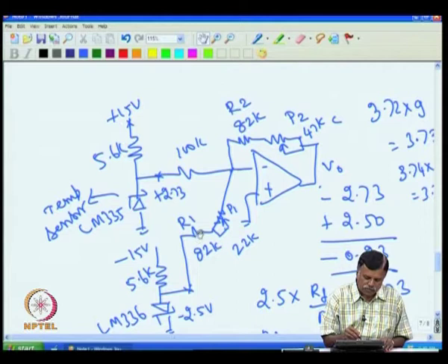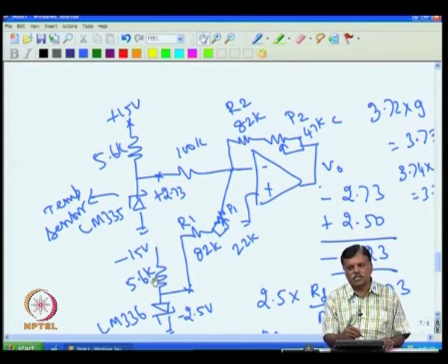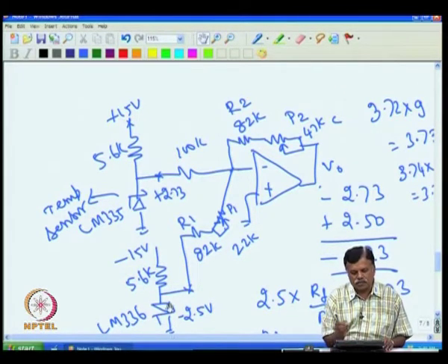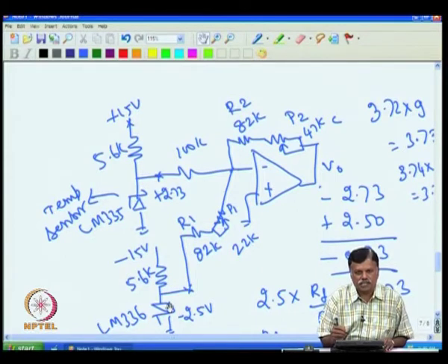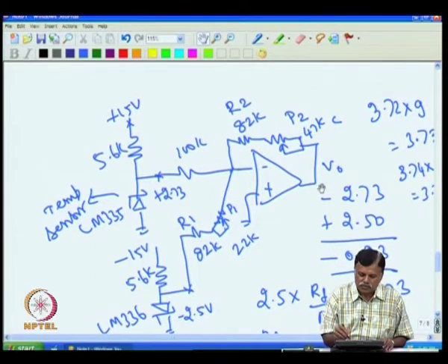So, the 2.582 K is only a very small current, that will still maintain 1 milliampere current through this. So, no issue, I can put this 5.6 K. That completes the circuit design for the temperature indicator. Of course, the output is minus. For example, even if it is 100 degree C, this is going plus 3.73, that will come as minus 1 volt here.